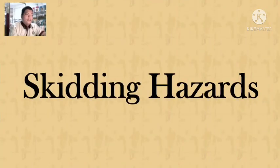Last, skidding hazards. Skidding hazards are caused by water on the surface of a pavement, polished aggregates or excess asphalt, or other lubricants on the pavement surface. Maintaining a pavement which allows water to flow off the pavement is a basic consideration.